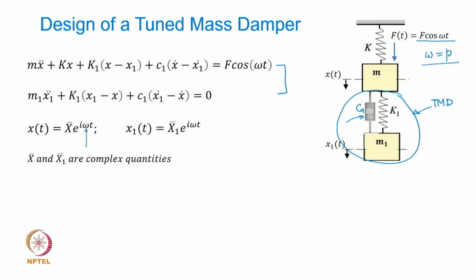The only thing is, because the damper is now accounted for, we can't ignore the phase, and that gets accounted for or included. Either you can write e to the power j omega t minus phi, or another alternative is to use a complex constant for this assumed solution.